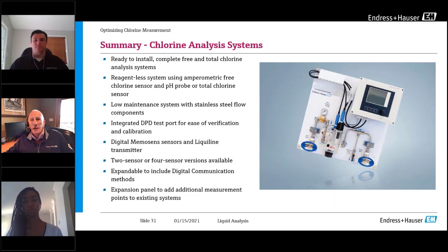Chlorine gas, you have to be careful, obviously. You have to plumb your gas lines in and get your system set up to be able to deliver that chlorine gas properly. Liquid chlorine or granular chlorine is actually a little bit easier to add to a process and use. So there's some advantages from that standpoint.